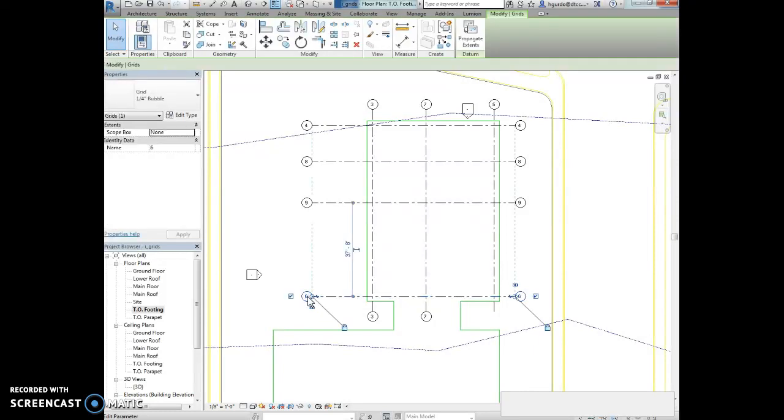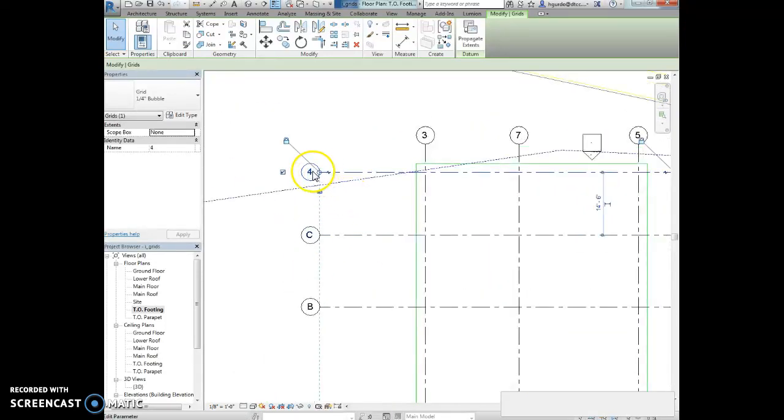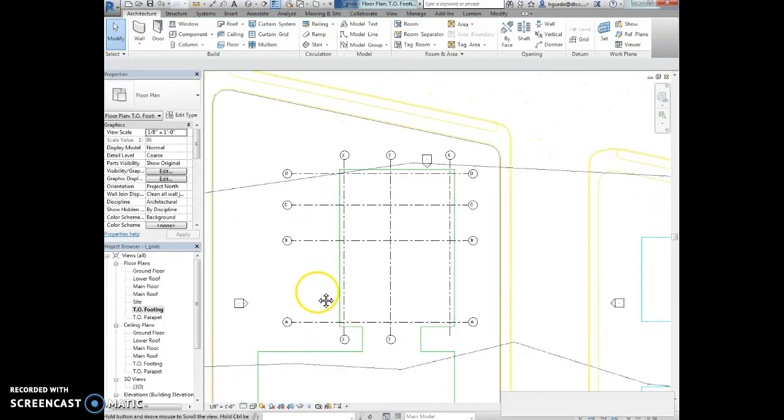So this 6th one, we're going to start off, if we double click in there, we're going to say A. We're going to click in the 9. This is going to be B. You may have to zoom in to do this so you don't accidentally click on something else. If you double click and it opens it in another window, it means you're trying to edit the grid line. Just close out of that other window and come back into here. It can't make it do it for some reason, but I imagine somebody might run into that.